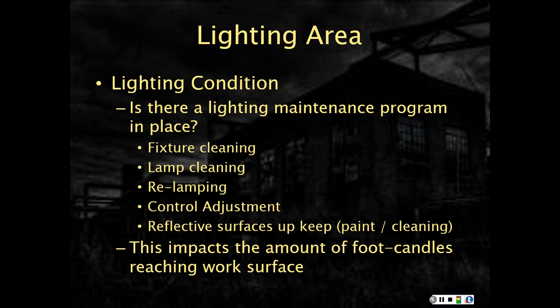Now, this will become crucial when you finally get your lecture on lighting. That's still to come. There are certain types of lamps that have a depreciation factor over time. In other words, they still use a lot of energy, but their light output drastically drops. Relamping ahead of a complete burnout brings back the efficiency. So it's actually more cost effective than simply doing what most people do, and that's wait for a lamp to completely burn out.